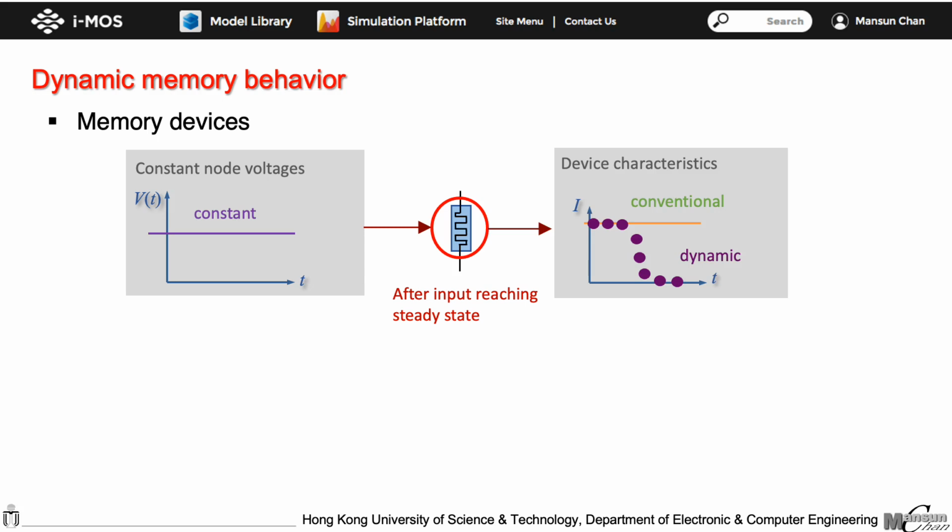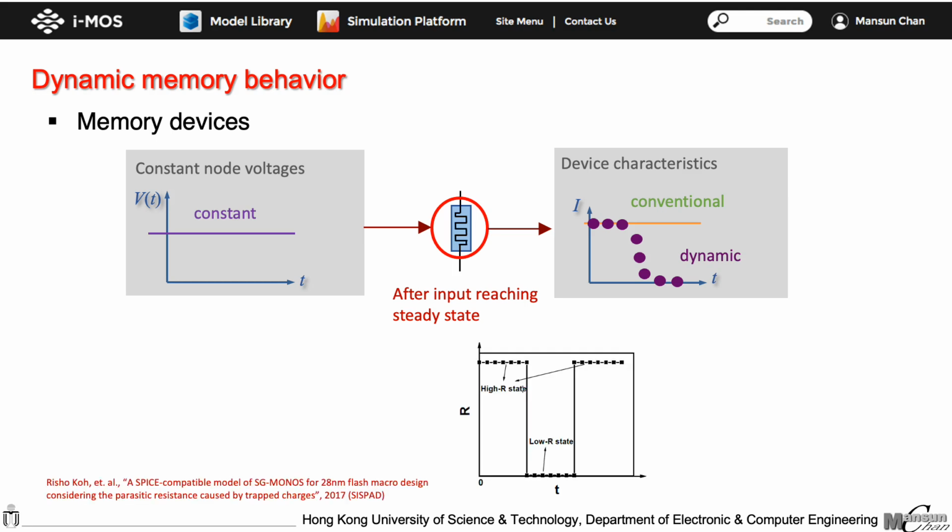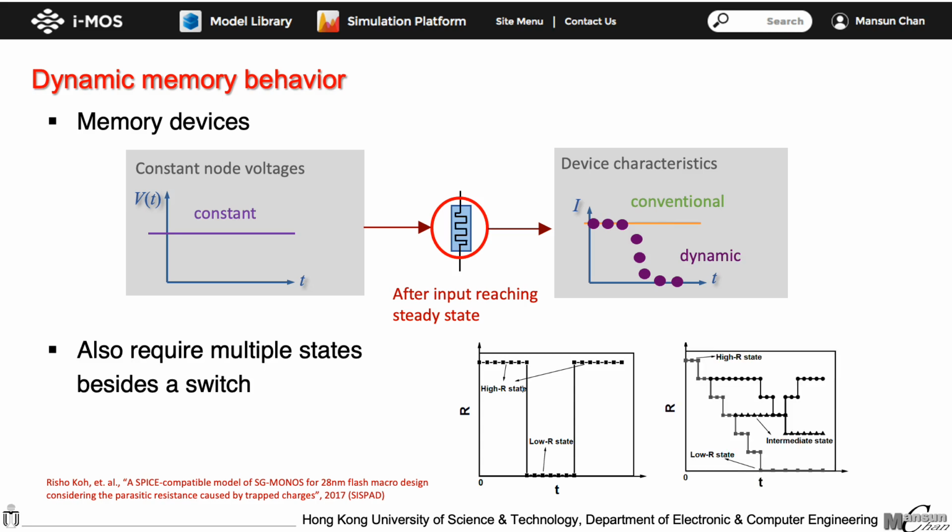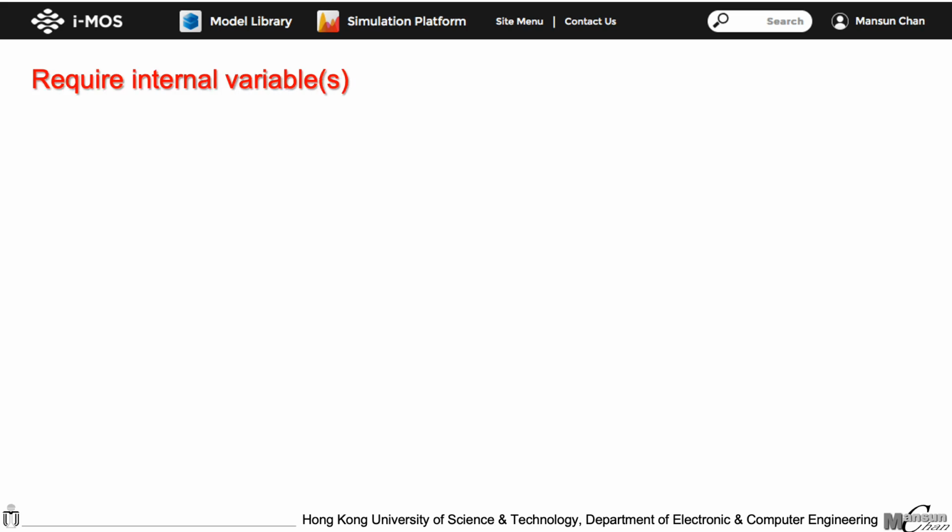In traditional memory modeling, it is also common that the states of the memories are modeled by a digital switch between two different states. For the purpose of neuromorphic computing that requires analog memory, it becomes necessary to handle memory elements with different resistance states, which are controlled by terminal voltages, as well as the time of the bias being applied. So, how to properly model the memory characteristics?